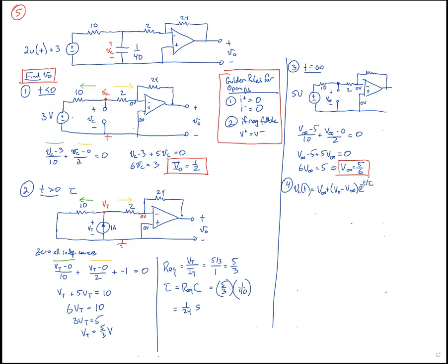At time equals 0, this goes to 1. So it's as if the exponent has turned into 0. E to the 0 is 1. So the V of infinity is canceled, and we're just left with V naught at time equals 0. That's right. For a really long time, this goes to 0, and we're just left with V of infinity. So I remembered it right.